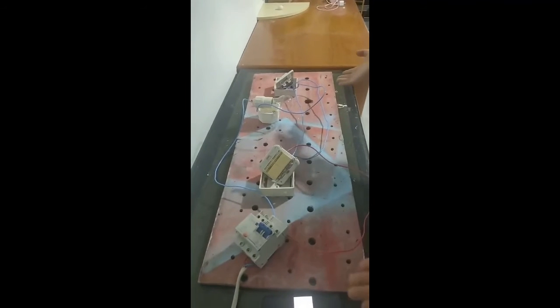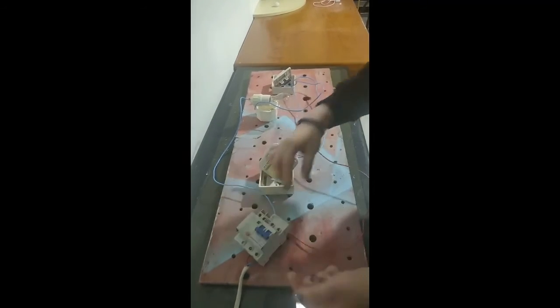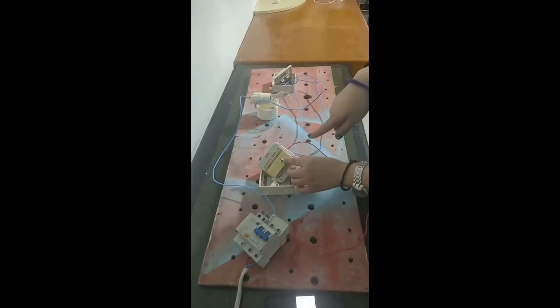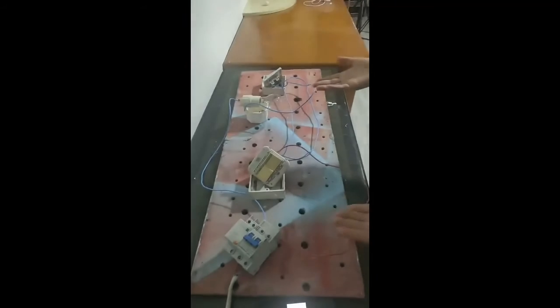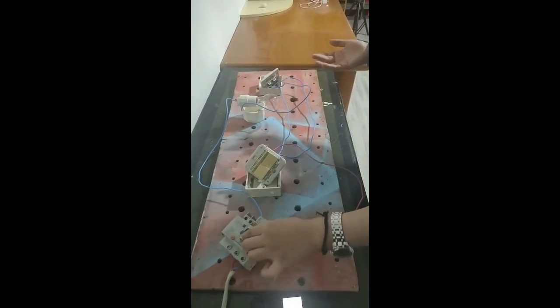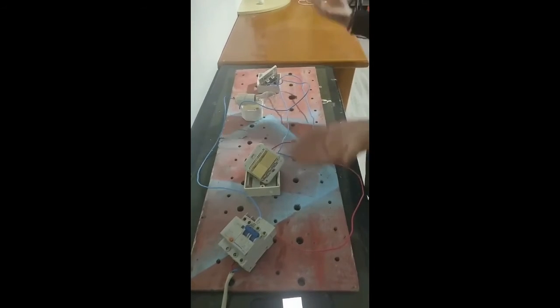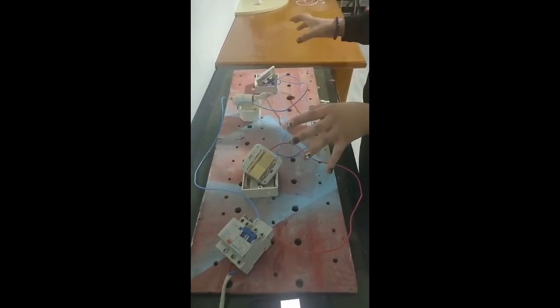So let's test whether it works or not. Okay, let me turn on the power source. Okay, it doesn't work, right? So we turn on the switch 1. Yeah, it works. And we now test whether we can use the switch 2 to turn off the lamp. Okay. Oh, it works. And also, as I turn on the switch 1, we can still use it, right? It still works. And I turn off with the switch 1. Okay, that is how we achieve our goal. Our goal is to control one bulb with 2 switches in 2 different places.